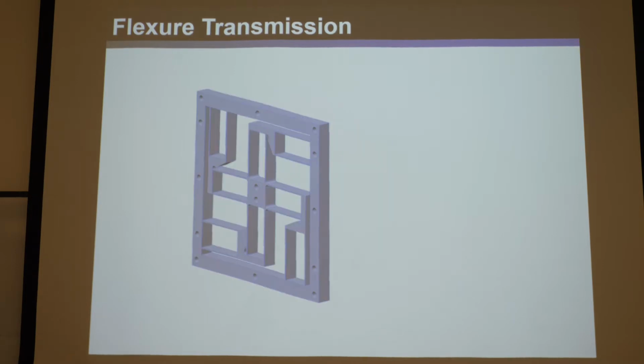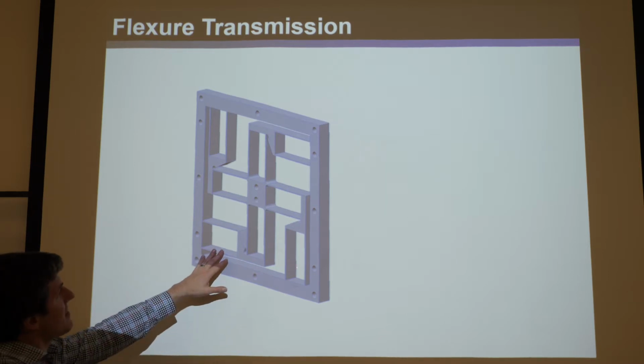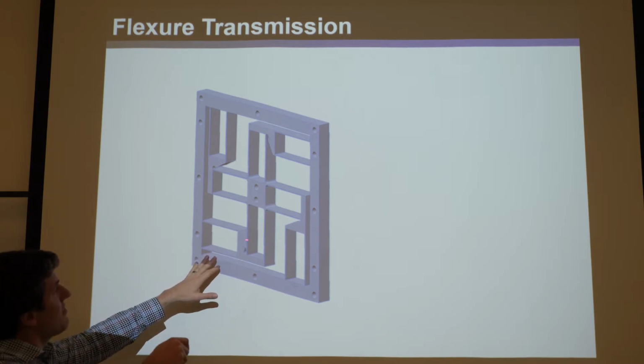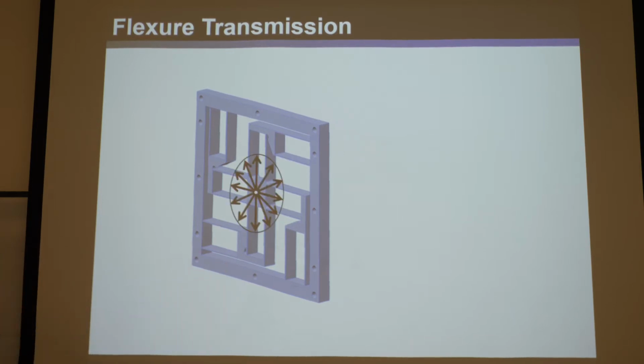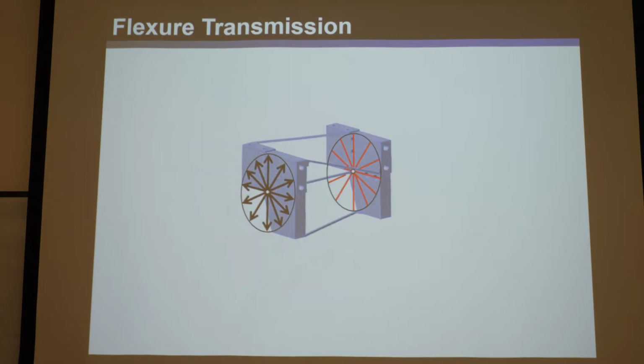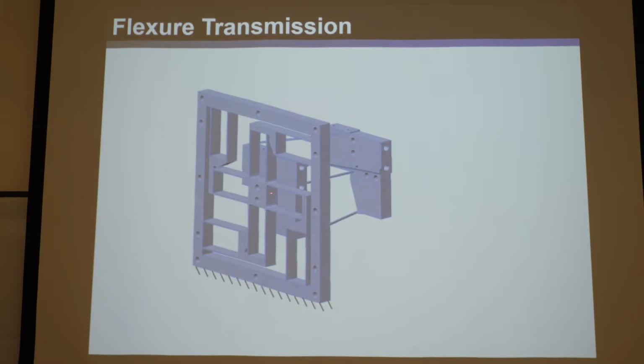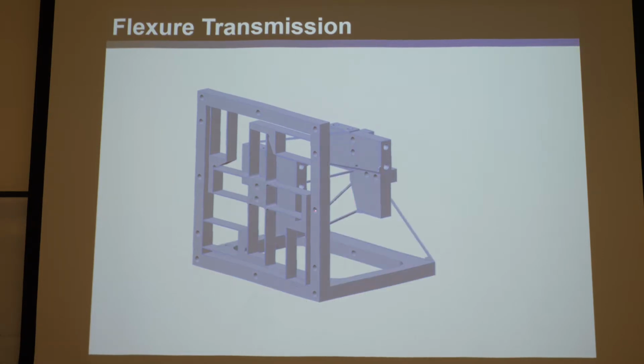Elastomechanically. So this is a great flexure. It's very famous, that achieves just 2 pure translations. Okay, so you can see it's kind of like 4 serial limbs, in parallel. So it's a hybrid system, and we'll just slap that. It achieves that freedom space. We'll slap that on the front face there to force it and ground it here. So we force this to only translate, and then we're going to actually slap some flexures on the back here to force only these rotations in the disk.